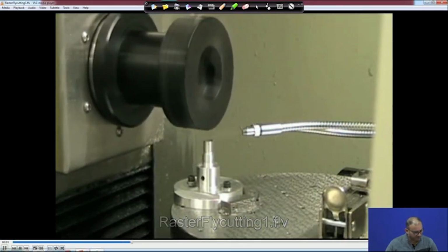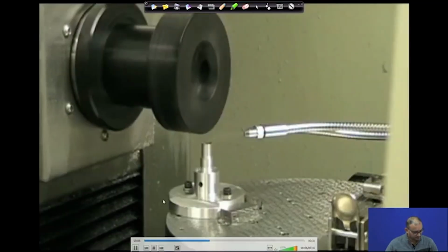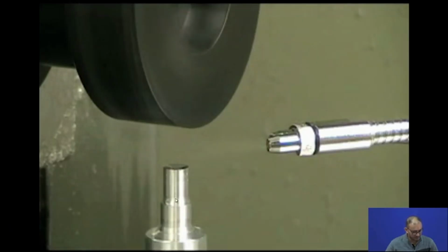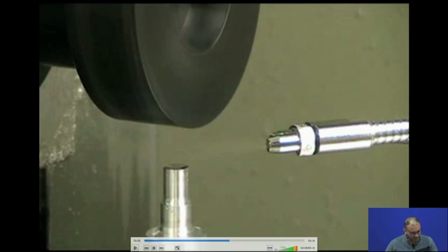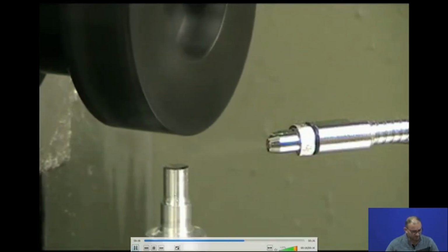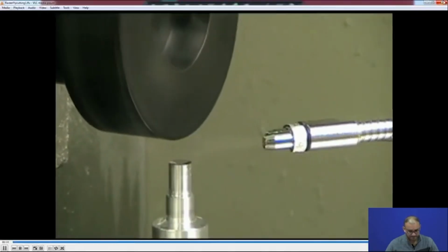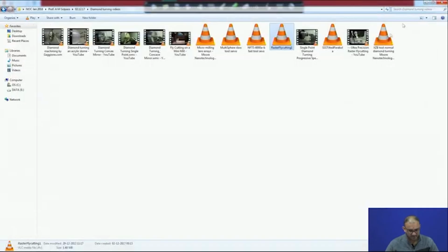So, what is happening in the fly cutting? Here what we are doing, that our cutting tool is located on the spindle side, and it is a single point cutting, your workpiece is located at the bottom, and then you rotate the workpiece here in its own axis, and then you rotate your cutting tool in this direction, so that it do the machining operation. It is not visible here because it is rotating at a very high RPM.